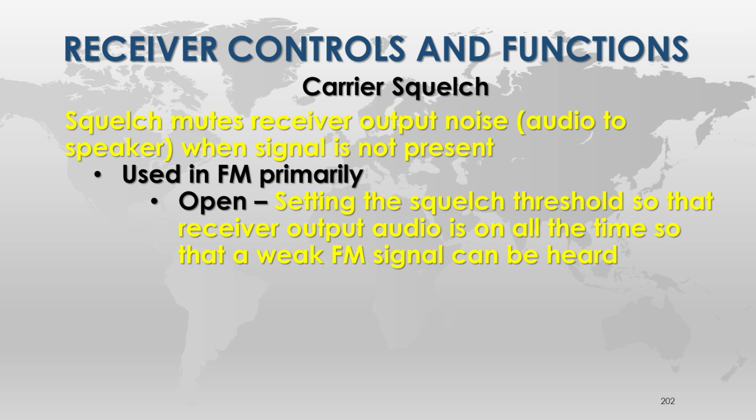The advantage of opening it up is if you're listening to somebody on simplex and they have a weak signal, you may only be able to hear that station if you open up the squelch. The squelch is tightening it down enough that that signal will go away. I can set the radio for an open squelch, but it means going into the menu and doing a bunch of steps. So hitting the button is a temporary way to just listen for that signal. And if you open the squelch, you're going to probably want to turn the volume down. It's actually easier to hear a weak signal with the volume down and paying closer attention.